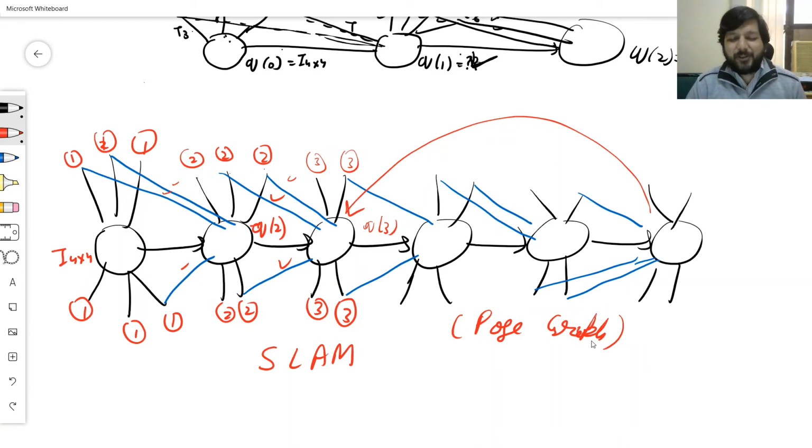But then eventually what we observed was that the observation model had a bigger problem, and that was it assumed the positions of all landmarks were known. Because the position of the landmark was known, I could calculate my position knowing the landmark's position with respect to me as sensed by the LiDAR or the visual odometry camera.